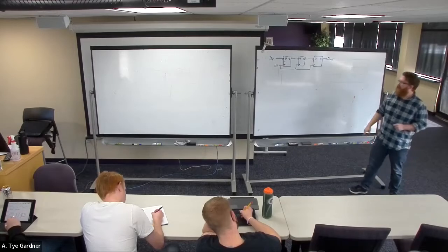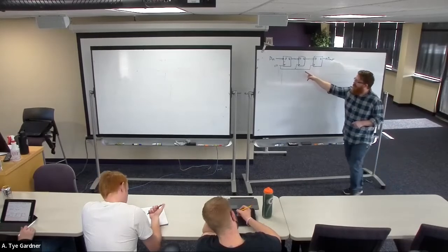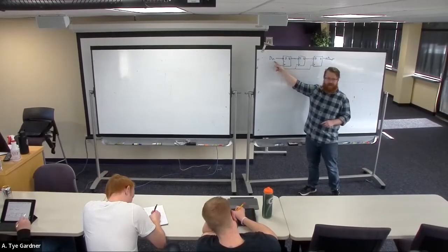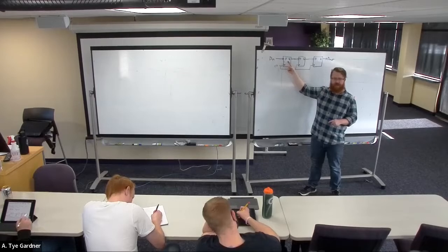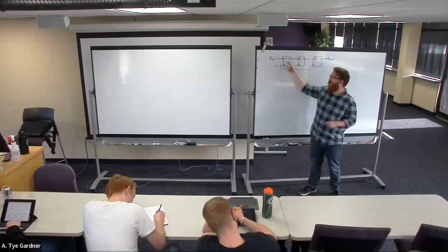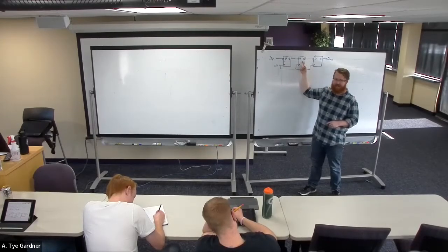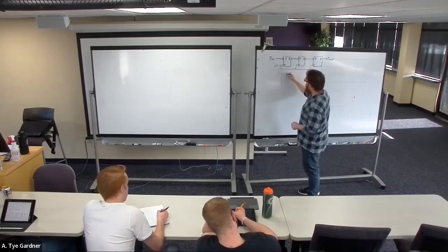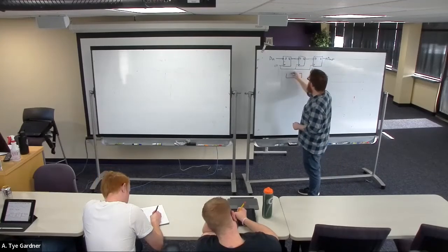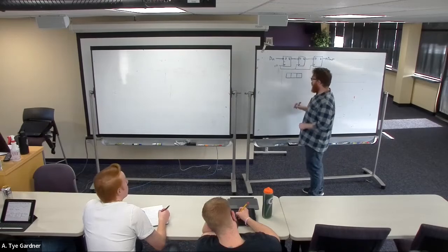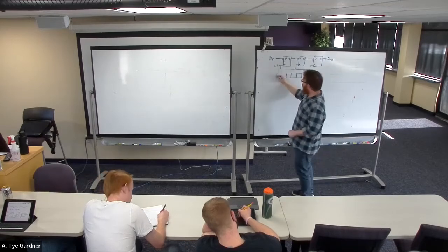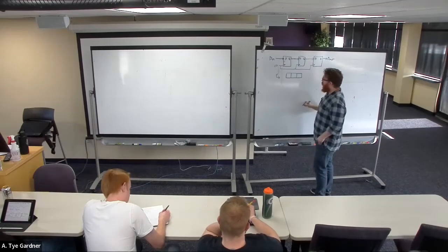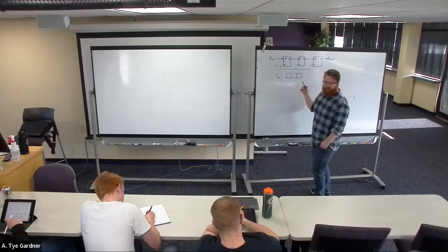All it's doing is at each rising edge of the clock, it's going to take some data in and store it in the first. Then at the next rising edge of the clock, it's going to take whatever is in the first and pass it into the second and bring in the new one. So conceptually, it's going to look like this. At time 0, it's empty.